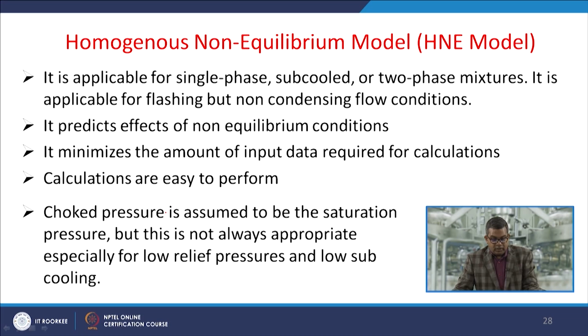The choked pressure is assumed to be the saturation pressure, but this is not always appropriate, especially for low relief pressure and low subcooling. So, while using this particular model, you must know what is the concept of low subcooling and low relief pressure.